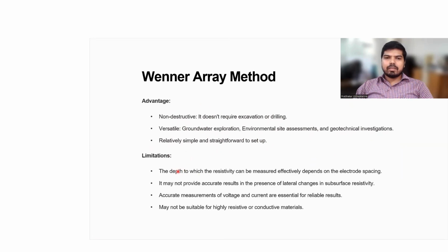There are a few limitations. The depth to which the resistivity can be measured effectively depends upon the electrode spacing. It may not provide accurate results in the presence of lateral changes in the subsurface resistivity. Accurate measurement of the voltage and current is essential for accurate results. Sometimes it may not be suitable for highly resistive or conductive material.